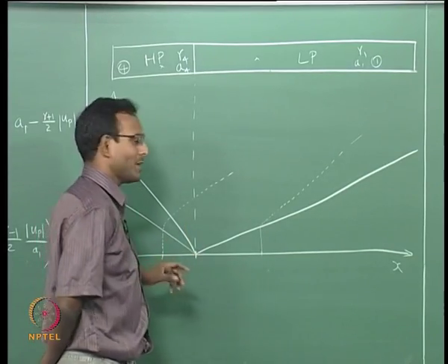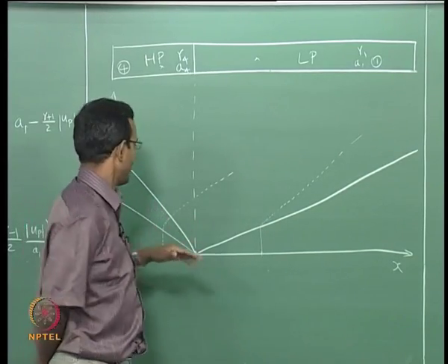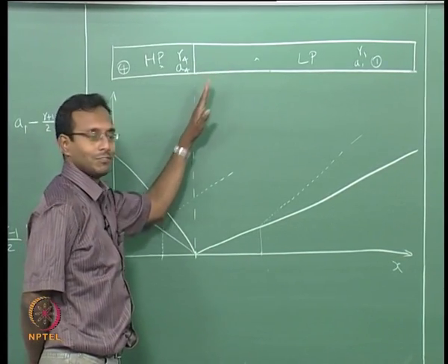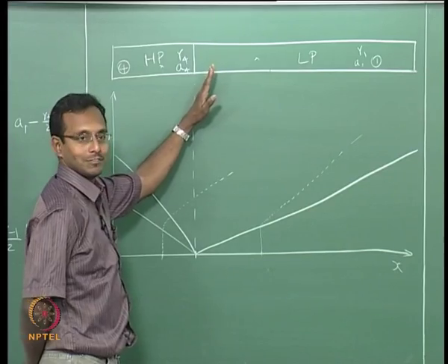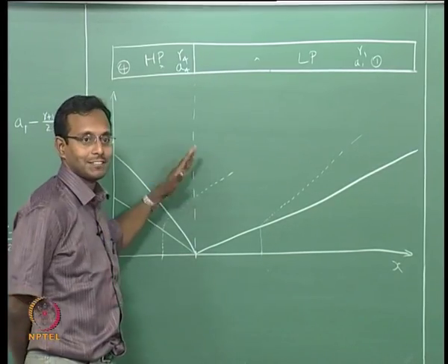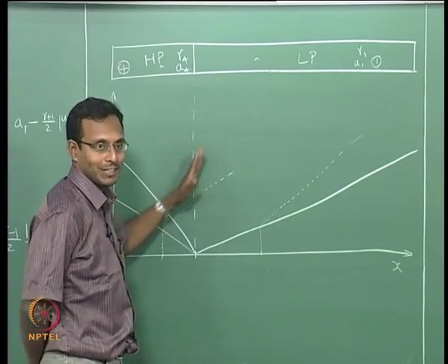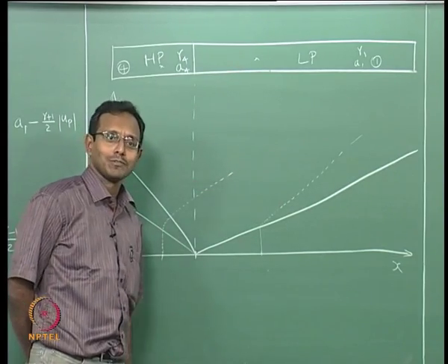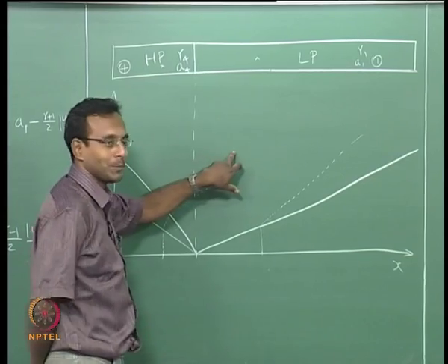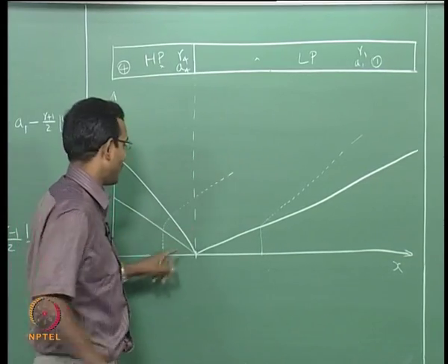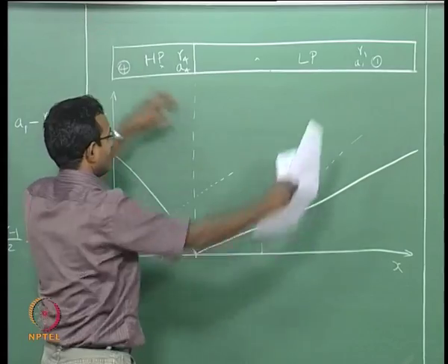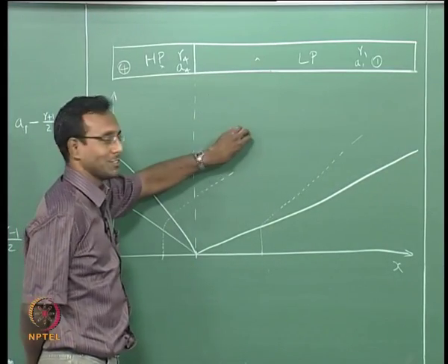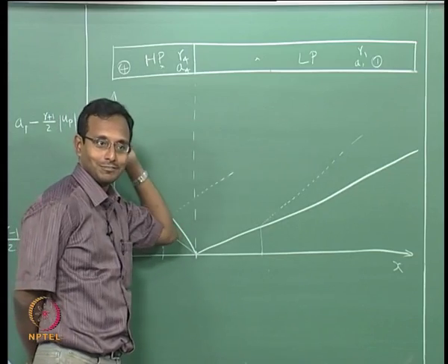Okay. Maybe the other thing might happen. Maybe this thing is going far away like this. If it is going out like this, very low velocities, dx by dt is less, that means it is almost vertical, it is going like this. If it is going like this while that one is traveling faster, what will happen now? There will be empty space created, because the fluid element here and here are now diverging, the space in the middle will be empty. That means there will be expansion fans from here going all directions.